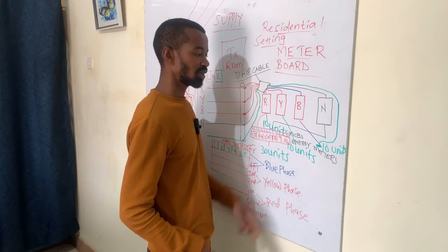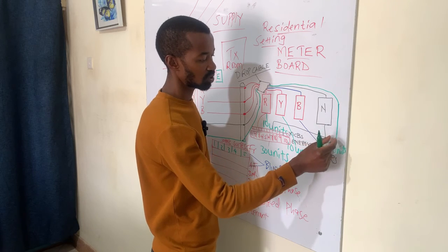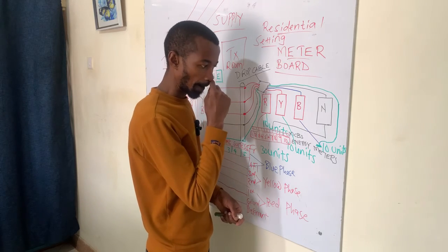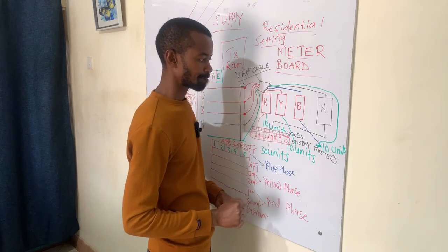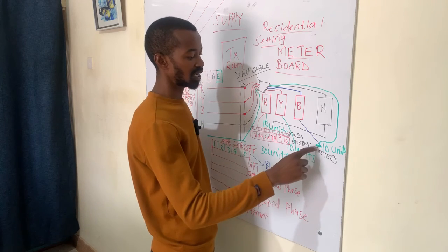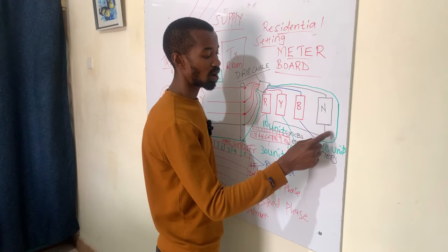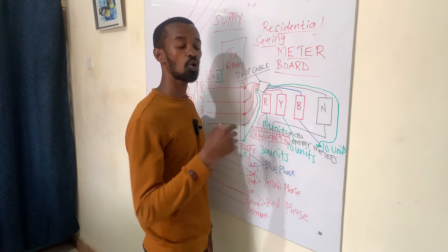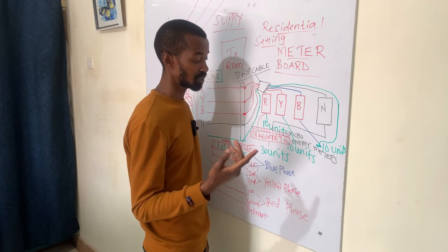All right. So if you have a loose connection, in most cases you'll find that this connection here, because it's an earth connection, does not have a lot of strands, or it is not bigger in size compared to other conductors. So if you have a loose connection here, power will tend to utilize this green path here. And in most cases, you find that it burns the entire cable insulation, exposing all of these wires in the air. Those are scenarios which I've experienced, by the way.